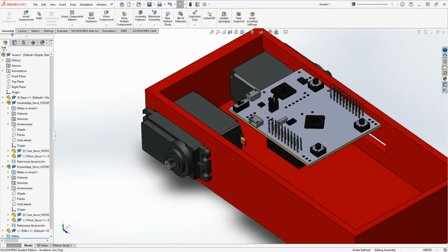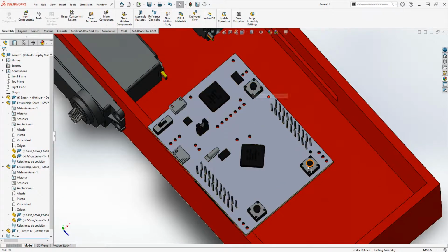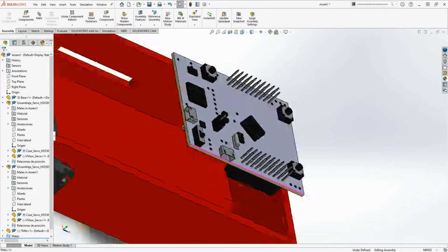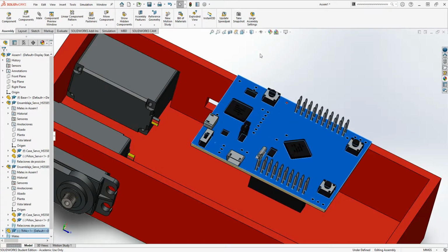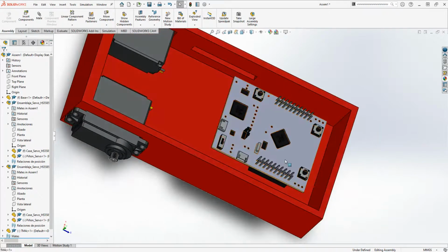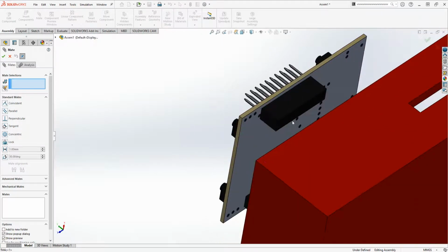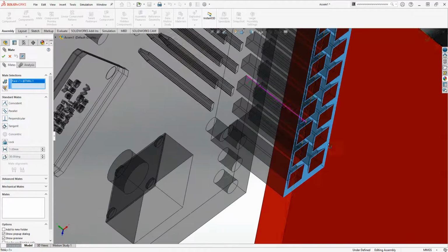How snug do you need to make these fits? That's very objective, depending on what you're making. What I would recommend is trying to 3D print little slots. Experiment using the makerspace, or Texas Invention Works as it's now called, and see what fits and what doesn't. See how much the printing material expands or contracts during cooling or heating. It's a great idea to experiment with those things firsthand. You'll be able to see a lot better whether the difference is 1/100th of a millimeter or 1/5 of a millimeter, however much it takes.